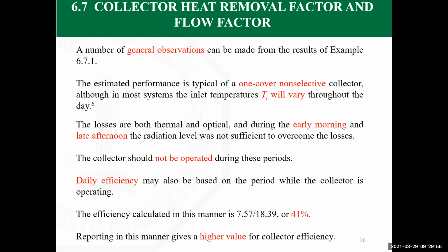Maybe the temperature of the fluid is higher than the outlet temperature after passing by the collector, and it will be a loss to do that. You're going to consume electricity in running the pumps, and at the end, you are not going to get heating at all. That's why the control system would allow the pumps to operate when you reach a certain temperature, for example.